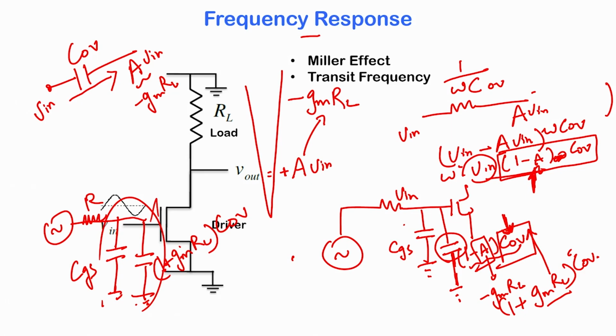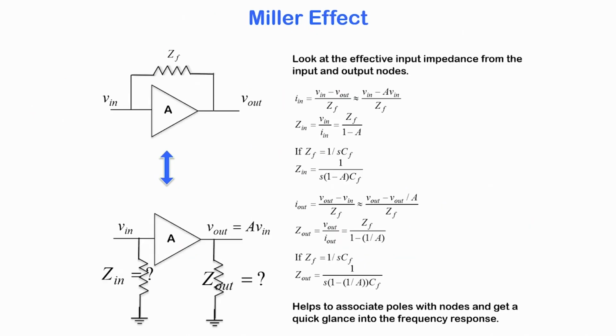Okay. So there are many ways you can make use of the Miller effect also. You can artificially create a pole, so as to say, to stabilize the response of amplifiers, etc. But nevertheless this is a problem that you must be aware of. And it is not only true for MOSFET circuits or MOS capacitors. Here I have given you a slide where any amplifier with any feedback impedance across it will experience the equivalent of a Miller effect. So if you have the time, do go through these arguments, although I will not discuss it right now.